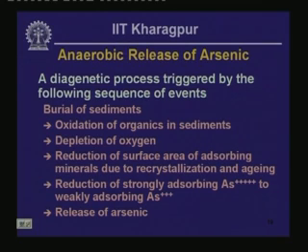Reduction also changes pentavalent arsenic that naturally occurs within the sediment to trivalent arsenic, and trivalent arsenic is weakly adsorbing in comparison with pentavalent arsenic, and that leads to release of arsenic in groundwater.